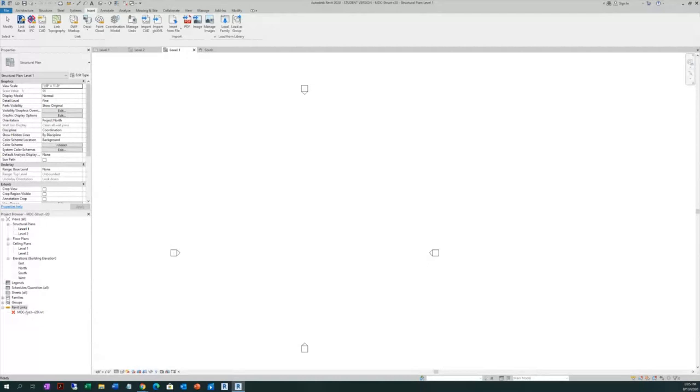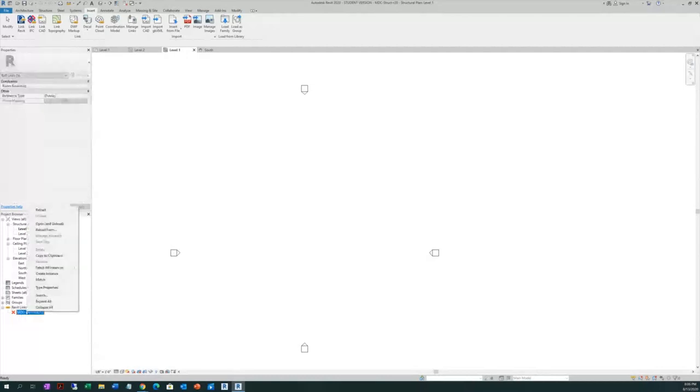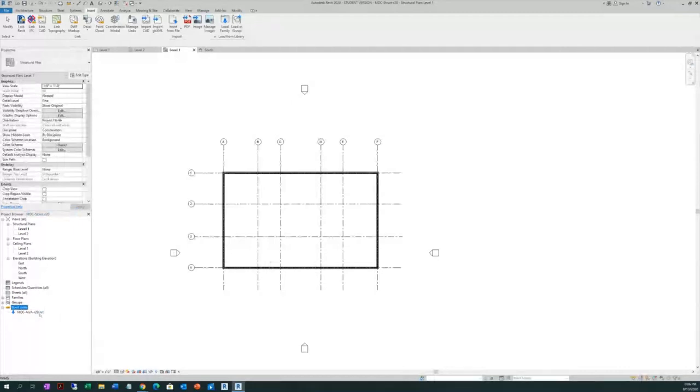Okay, so I want my Revit architectural file back, highlighted again. See the difference is, if the file is on the path set, I can just reload it, correct? But imagine that somebody else moved the file from the original folder. When I bring it here, that would be a problem.